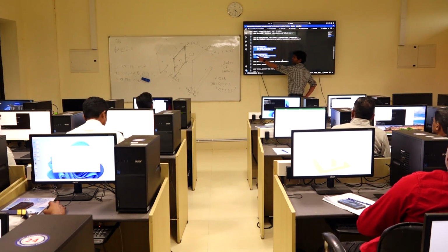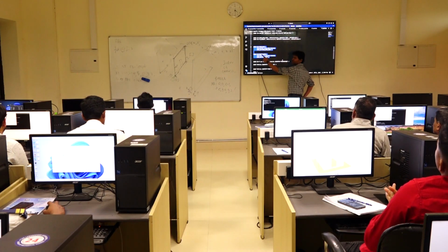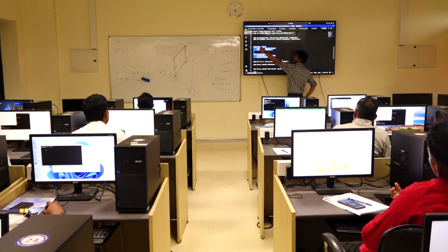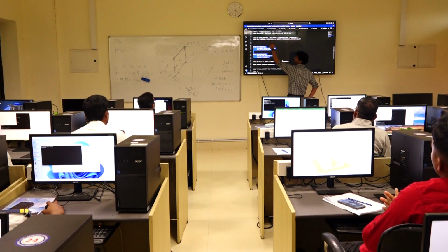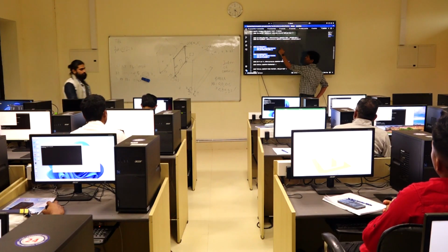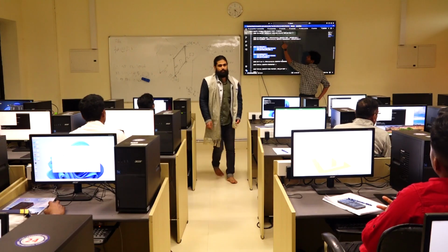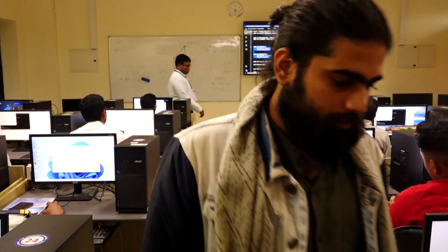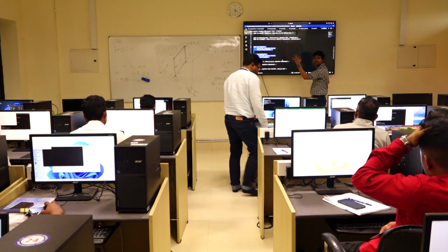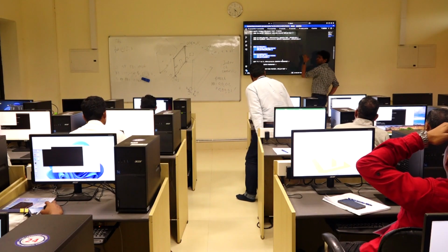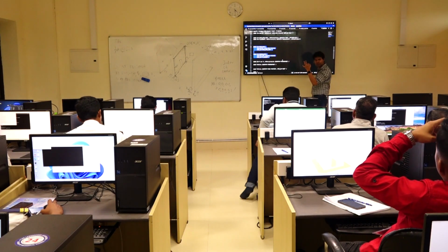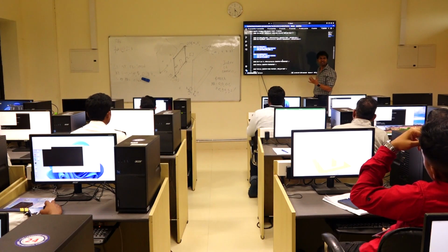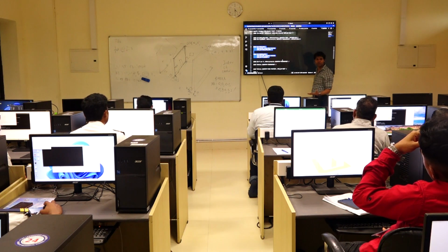So you create a hole, in the same line for the window hole you add a device, and for that device you specify the location close to the window, and you are opening the window at a certain temperature. So let's say if the temperature at that location close to the window reaches 200 degrees Celsius, then it is going to open the window.